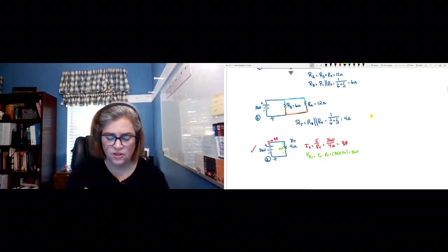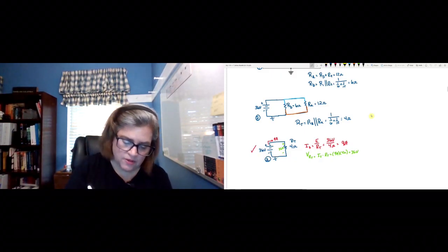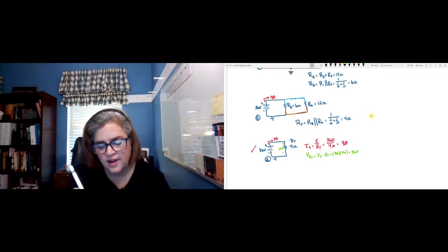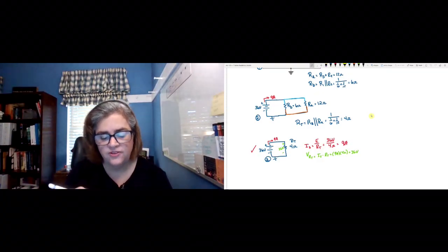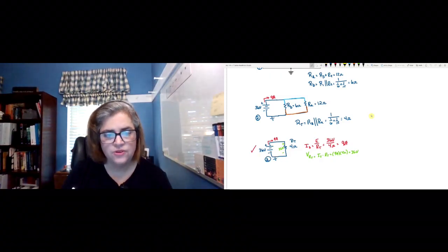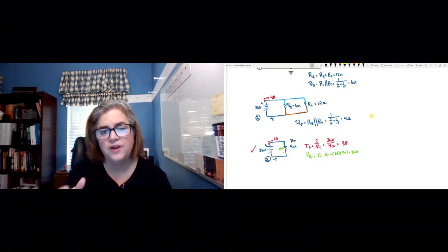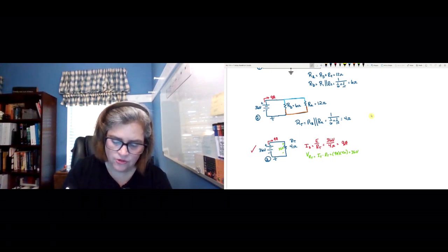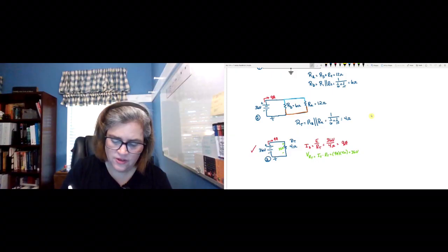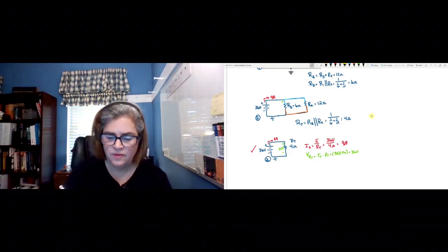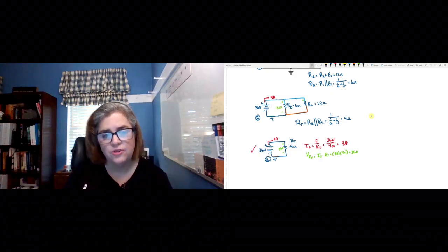So I'm going to transfer everything I learned from the third circuit up to my second circuit. I'm not going to go all the way up to the first just yet, but I know that I'm drawing 9 amps of current from that source, so that's not going to change. And this 36 volts across the 4 ohm resistor, remember, is across parallel RB and RA. And we know that in parallel, resistors have the same voltage drop. So that 36 volts is what I'll see across each of my resistors, RB and RA, which will allow me to find the current through RB and the current through RA.